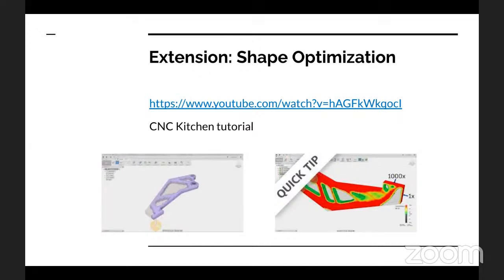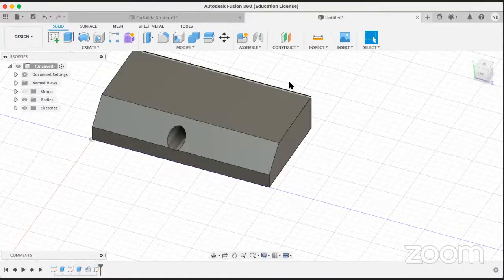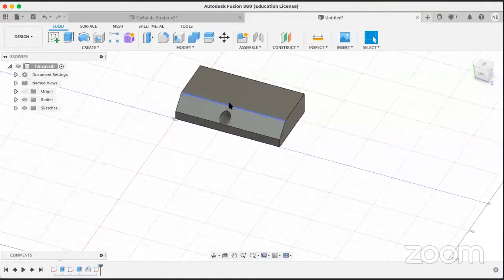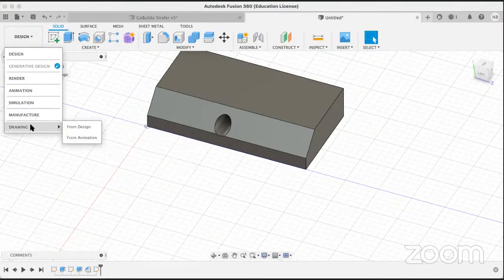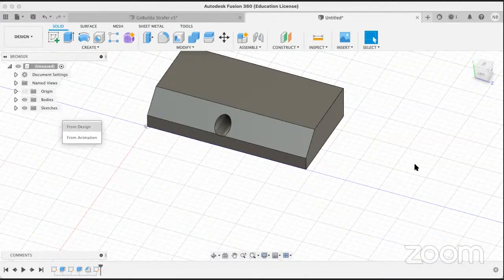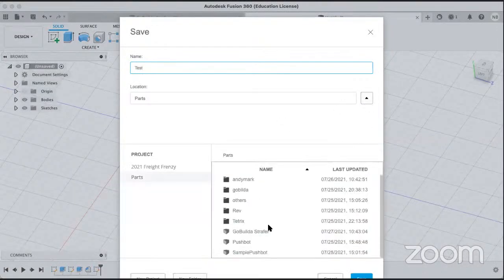Oh, I'm not sure about that. I've never. Okay, I'll just search it up and report. Right, here it is. Go to your Fusion 360. In design, go to the design option. There you'll see drawing. Yep, that's right, from design. And then you can choose the different views like top, side view and so on.